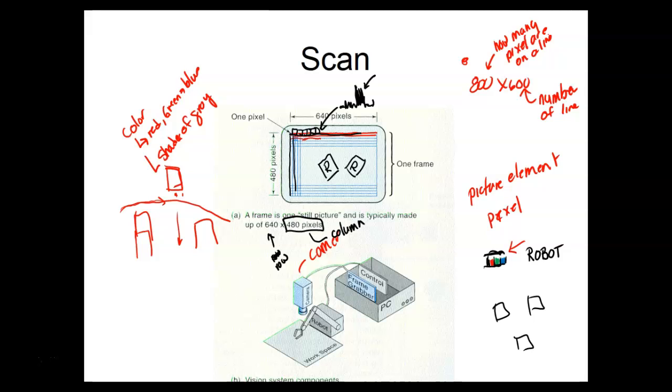They're just cameras. We mount them so they can see the parts we're looking at, then we program the cameras, and then the camera sends that information as an X, Y, Z. So for orientation, front would be X, then back and forth would be Y, and Z would be up and down, which is what robots use.